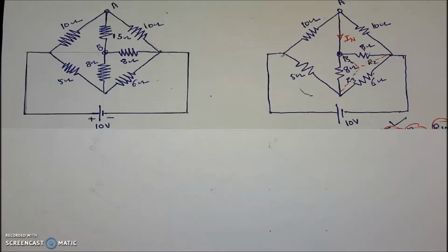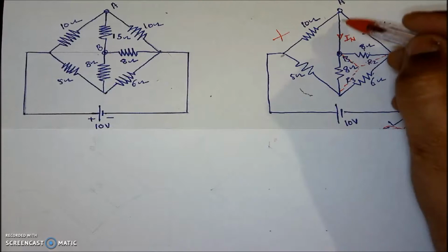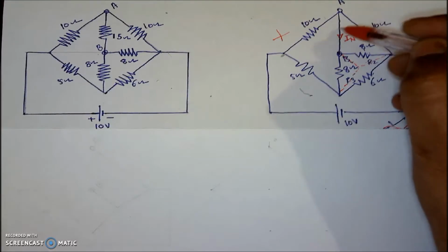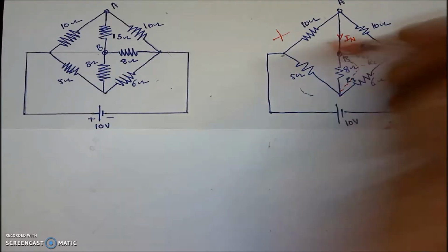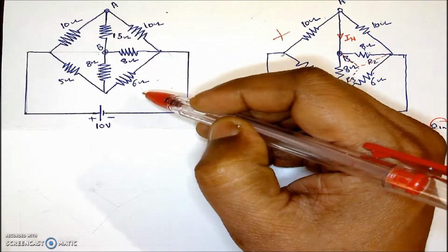Now for the calculation of Norton's equivalent resistance, we have to remove the load resistance. For that we should not refer to this figure, because there the short circuit comes into the picture. That's why I am referring to the main figure taken at the beginning of this example.